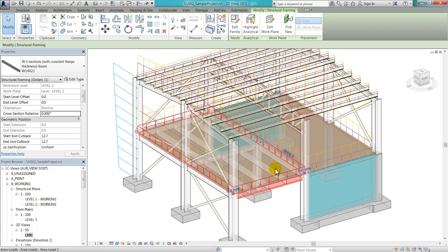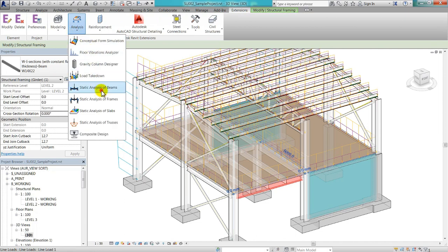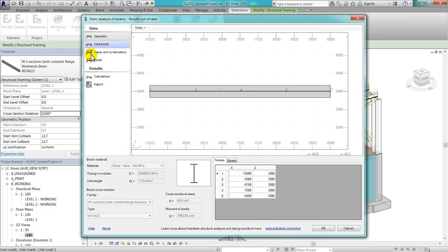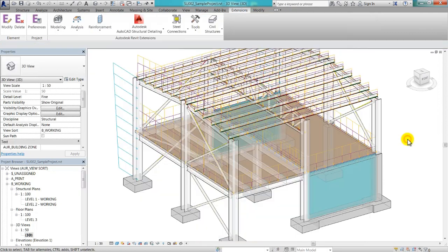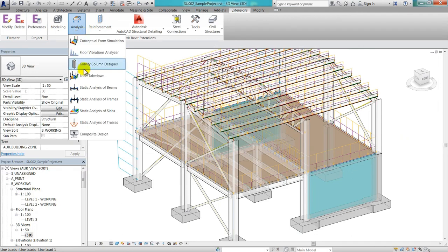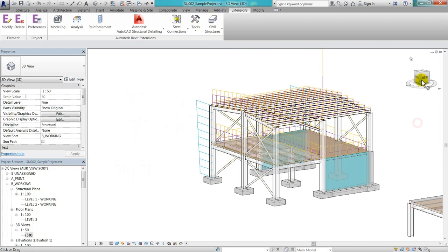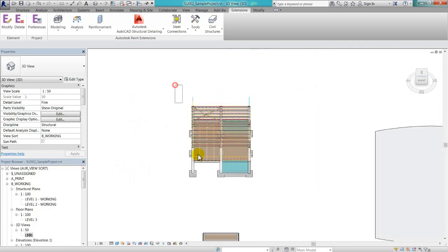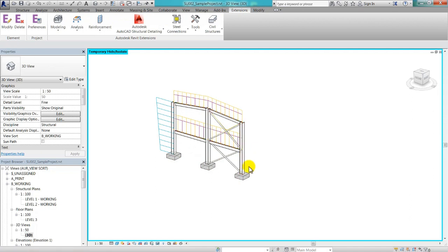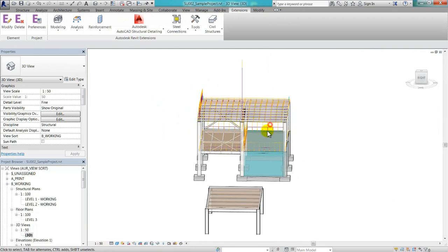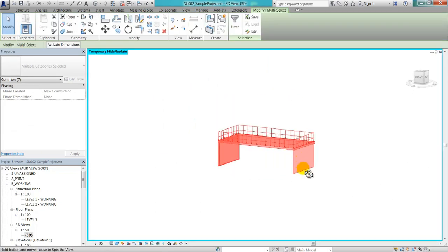Loads must be applied directly on the analytical lines or faces of selected elements. Tributary loads from connected elements, for example beams on girders, are not automatically recognized. Reaction forces created from the load takedown module are not taken into account either. The 3 modules for analysis of beams, frames and trusses work similarly. Therefore, the following exercises only guide through a frame analysis example and a slab analysis.